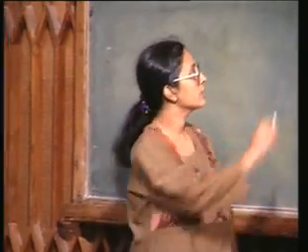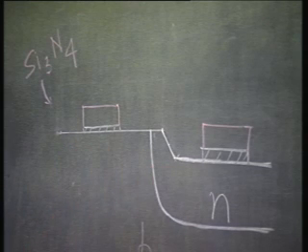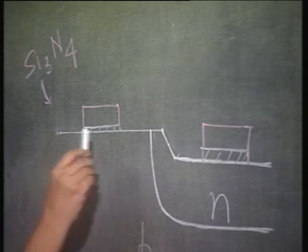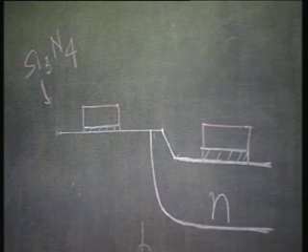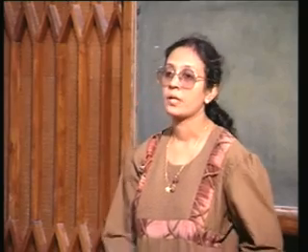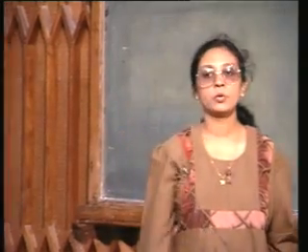Okay. So, after you have protected certain regions, you may or may not want to etch the silicon. If you want a recessed oxide, you will etch silicon to the required depth. If you do not want a recessed oxide, you do not have to etch, okay. But you do a boron implantation.